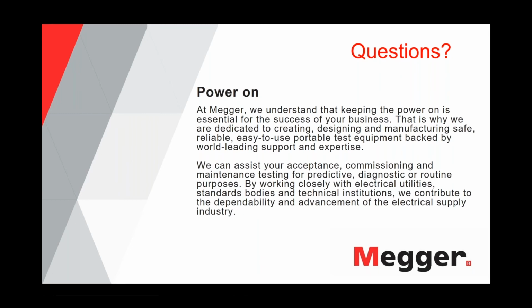Now, since you have the tree retardant XLPE since the early 90s, the degree of treeing is much, much less. So the current quality of XLPE treeing is about the same rate as EPR, so very, very slow. So it takes a long time actually to see substantial problems. In the past, this was not the case, where the trees were really showing themselves a lot and early on.